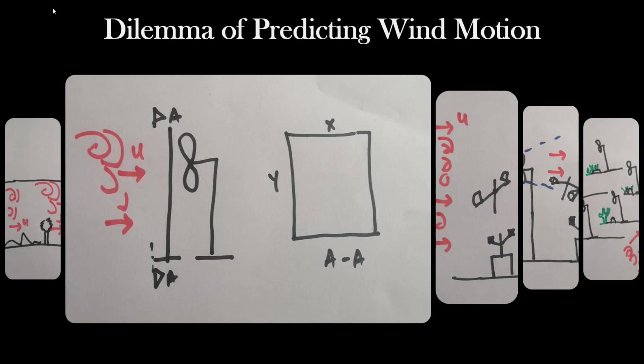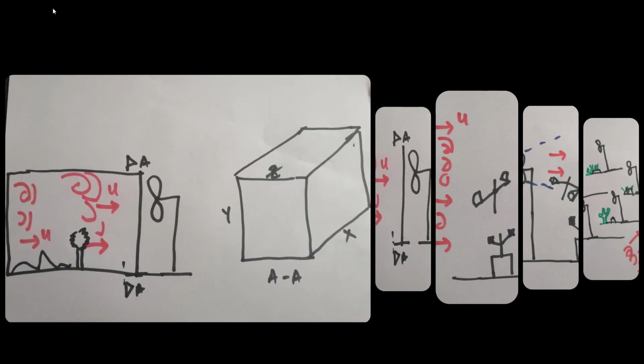You can see here the wind is on the left, which is the red, and the U is sort of your mean velocity coming to the wind turbine. There are some models that can provide you wind data for a two-dimensional plane, so for X and Y, just before getting to the wind turbine. What happens to the wind turbine afterwards is of no business of this kind of model. There are other models that can show you, for a certain distance, as the wind is coming in, how it's changing until it gets to the wind turbine. So you're talking of three-dimensional data, but it's only just before it hits the wind turbine, and that information is no longer relevant after that wind turbine.